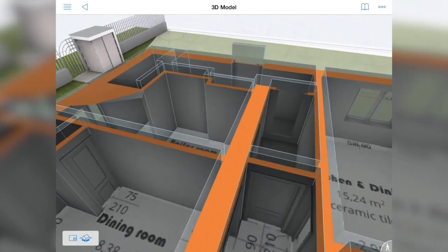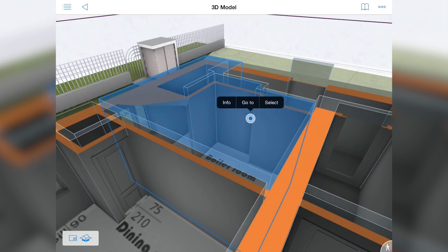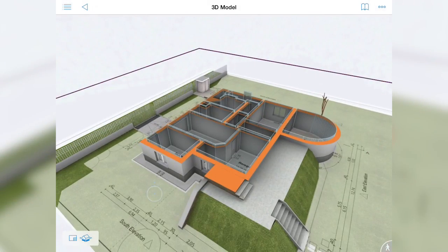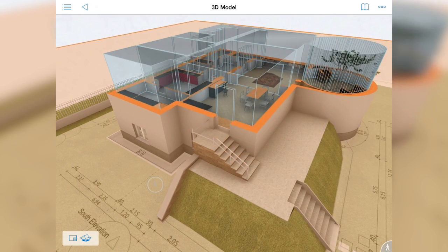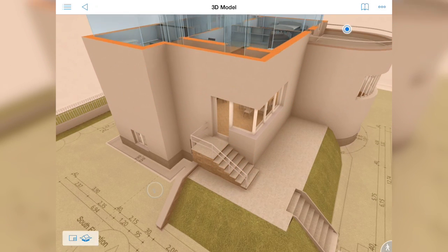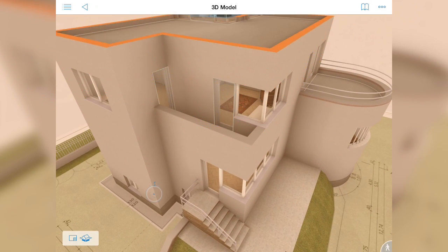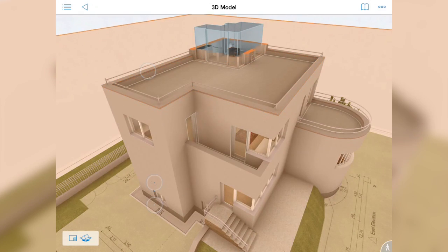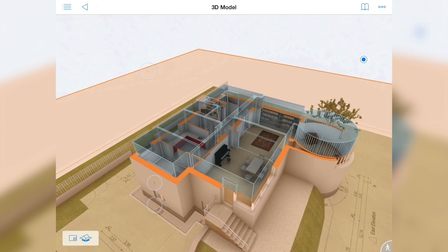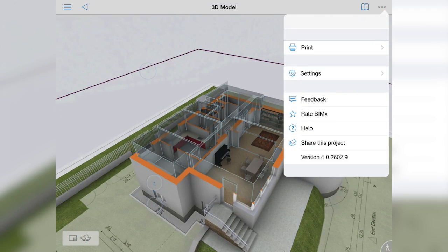In this case, BIMx will zoom to the 3D view of the selected zone with the horizontal cutaway of the building. Cutting planes never cut zone objects, but when moving a horizontal section to a different floor, BIMx will display zones from that current floor. If needed, the displaying of zones can be switched off again from the Settings menu.